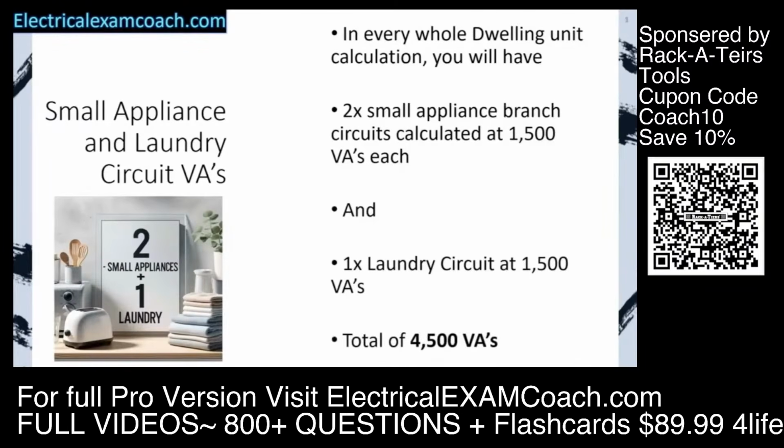Now this is something that we're only going to do and attach it to the general lighting load and receptacles before demand factors. We're only going to do it when we're doing a whole house load calc. We are not going to add it on to something like an individual dryer or an individual range.